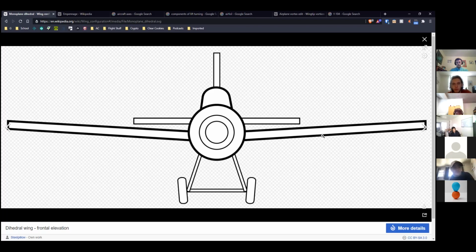So it would have a greater moment this way than this wing would this way. And so if you didn't change anything else, this wing would sink back down until they were equally banked again. Like each wing had an equal bank. Basically, the whole plane was level like this because of those forces changing. So you are basically hanging the fuselage in this bowl of the wing. And that creates roll stability, which is usually a good thing.